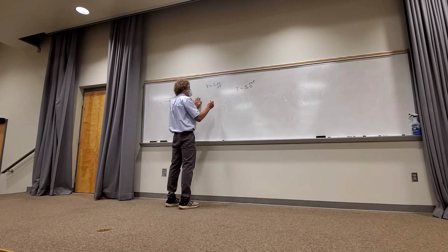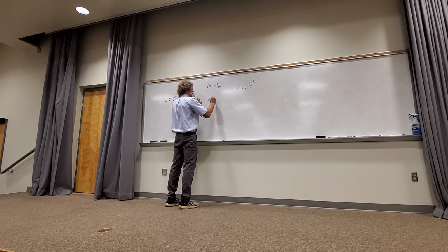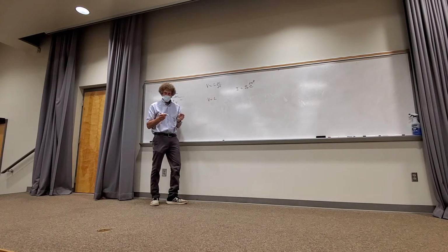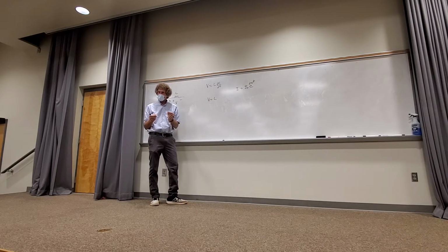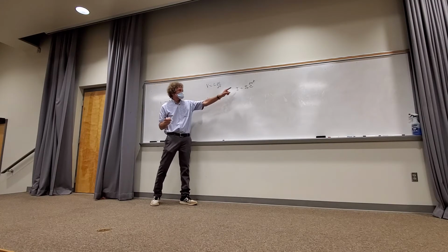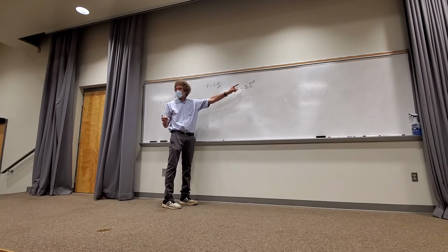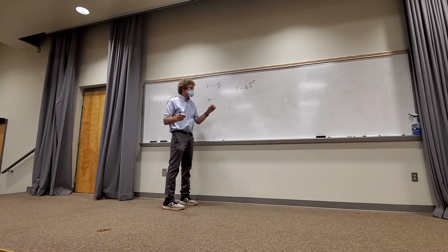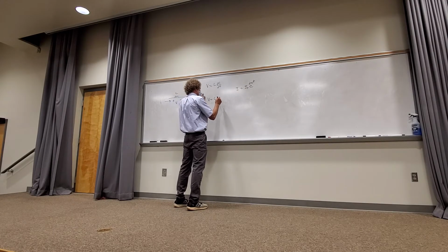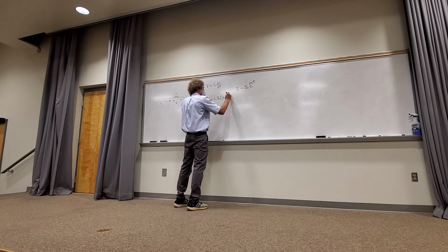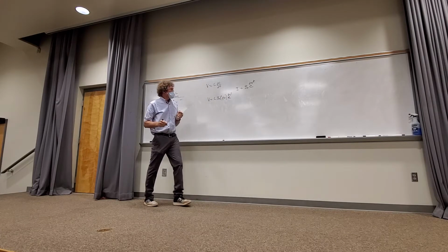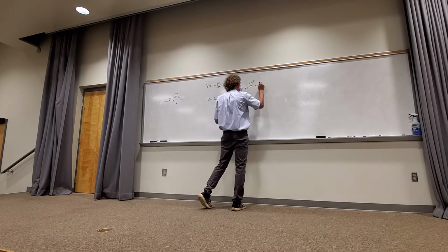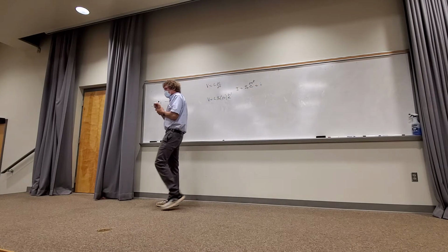That means V is equal to L times the time derivative of I right there. Do y'all follow me? The time derivative of I would just bring out the j omega. Do y'all see that? If you take a derivative of this with respect to t, only the j omega comes out. So it's going to be L times I naught times j omega times e^(j omega t). Maybe I can call this small i if that bothers you. Y'all with me on this?